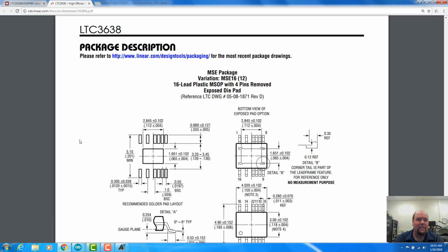Sometimes for high density PCBs, they'll have these really short electrical pads, and it's good for reflow, but it's really tough to get an iron in there if you're trying to do rework, especially with fine pitch packages. So sometimes I'll extend out these pads a little bit to make it easier on myself. I'm not going to do that for this one. We'll just follow the actual definition that's here in the data sheet.